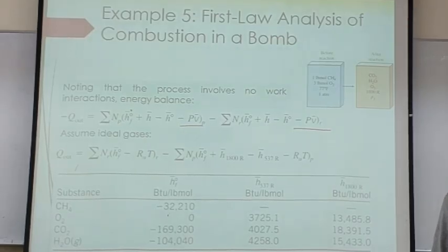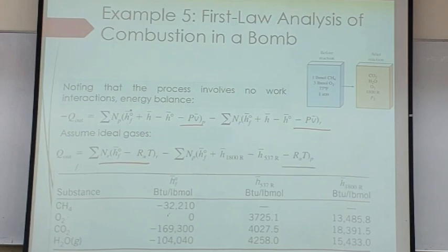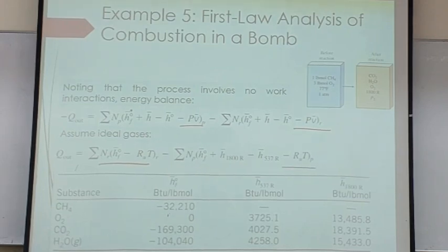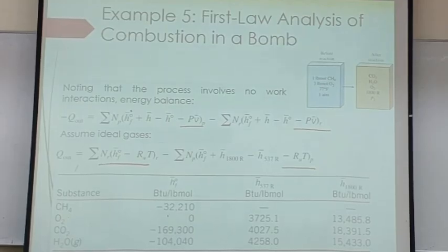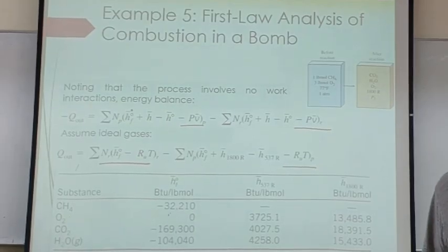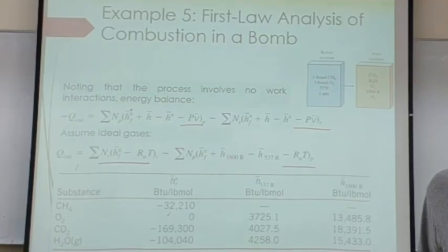And we also showed you that because PV is a bit hard, we use the ideal gas equation to replace the term. They change into RuT instead. Change the PV to RuT. And RuT is easier. The temperature we have, Ru we also have. Because the previous one, technically you can also use that, but then v is a bit hard to find. Then the rest is the same.